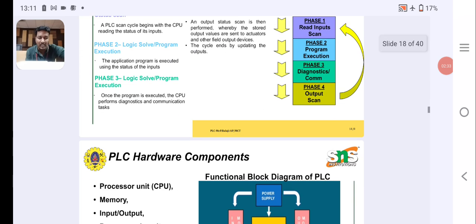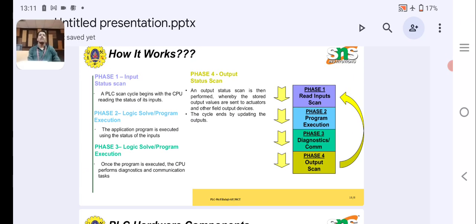It is shown in the functional block diagram. Also, generally any input must be present for longer than the cycle time. Special modules are available for use in such circumstances. Consider a PLC with a cycle time of 14 microseconds. What is the maximum frequency at which digital inputs can be detected? The maximum frequency will be 1 pulse every 14 microseconds, a frequency of 1 divided by 14 microseconds, so it may be counted at about 71 kilohertz.